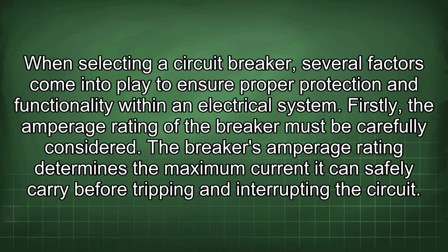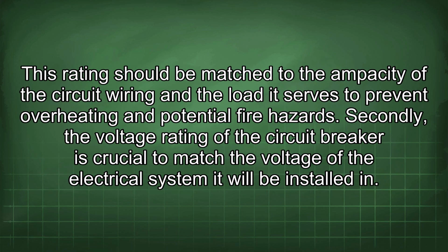When selecting a circuit breaker, several factors come into play to ensure proper protection and functionality within an electrical system. Firstly, the amperage rating of the breaker must be carefully considered. The breaker's amperage rating determines the maximum current it can safely carry before tripping and interrupting the circuit. This rating should be matched to the ampacity of the circuit wiring and the load it serves to prevent overheating and potential fire hazards.